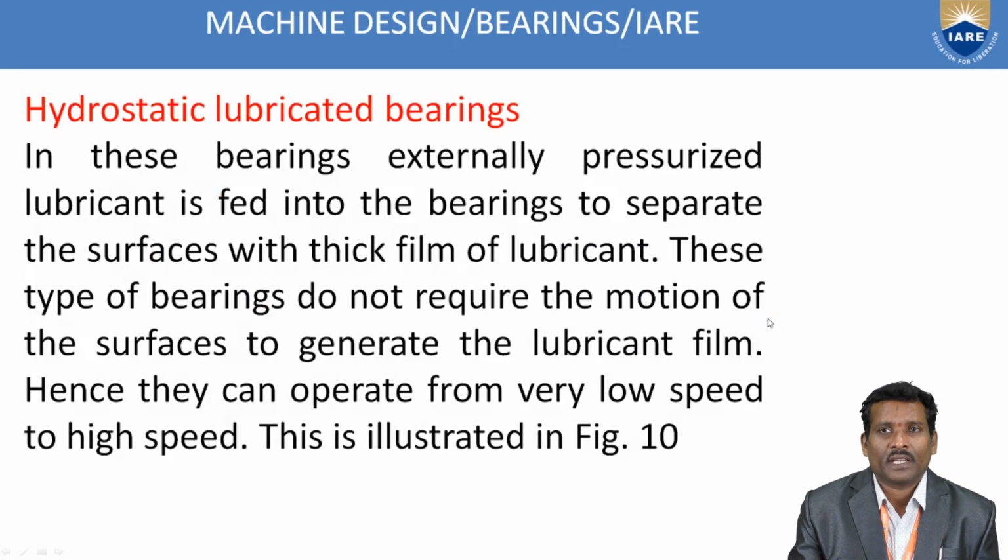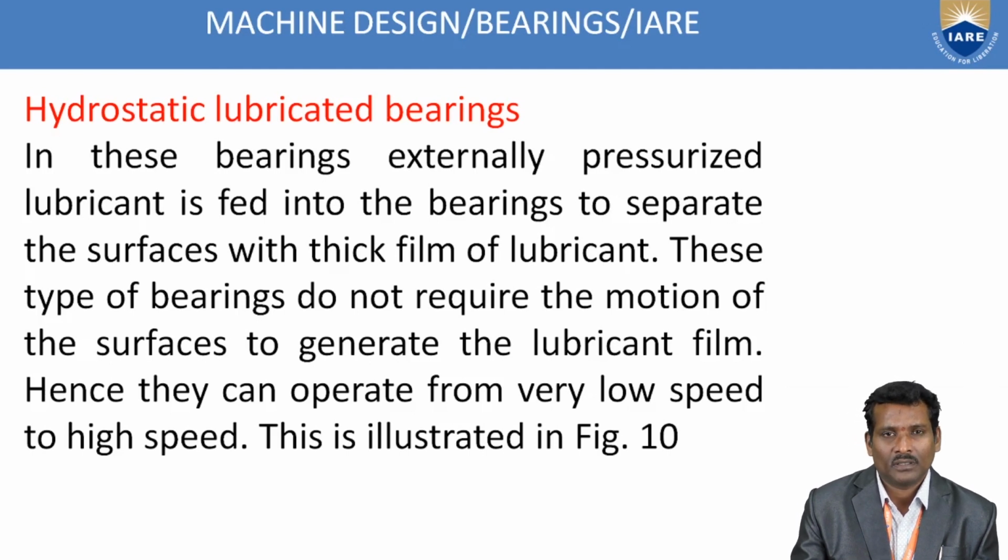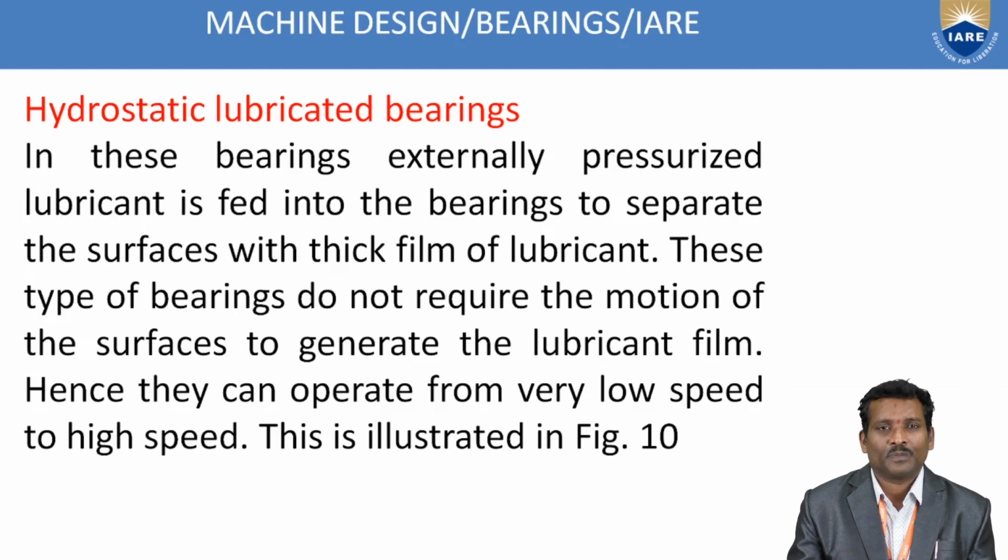The second case, hydrostatic lubricated bearings. In these bearings, externally pressurized lubricant is fed into the bearing. What is the necessity of pressurized oil? It is to separate the two surfaces, the fixed bearing surface and the moving surface. In hydrodynamic bearings, no external pressurized oil is needed, because while rotating, the journal itself generates sufficient pressure to carry the radial loads.